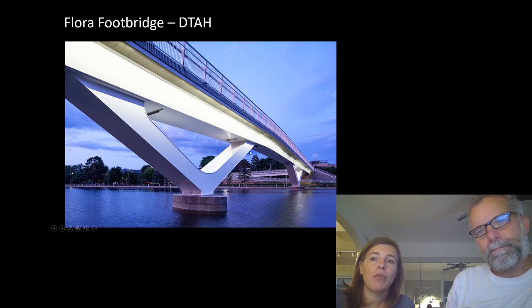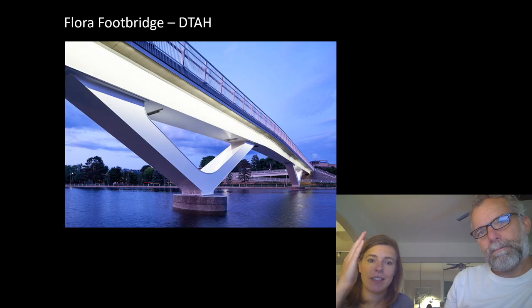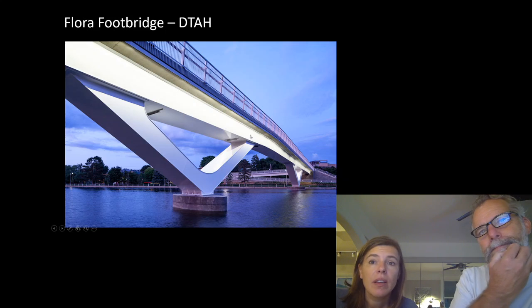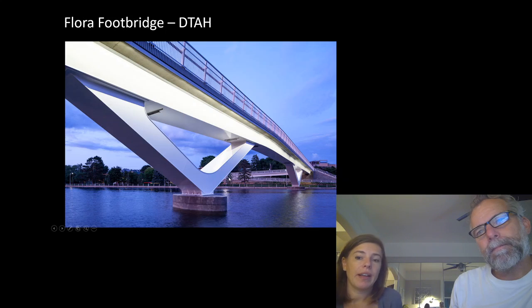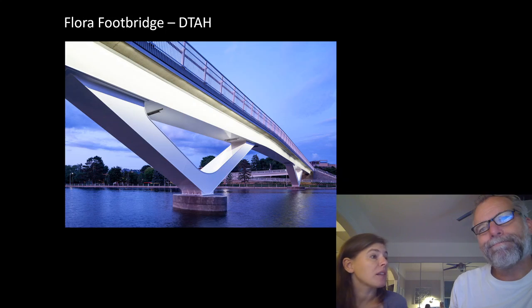The one thing about a fillet weld often is we usually like them in situations where it's upright or sheltered somewhat, because water can pool in there. So this fillet weld right here and this along here, that's where we're going to get standing water. So that needs to be ground smooth and painted to make sure that we don't have any chance of rust, because that's going to be the weak spot on a system like this. That's a good point.